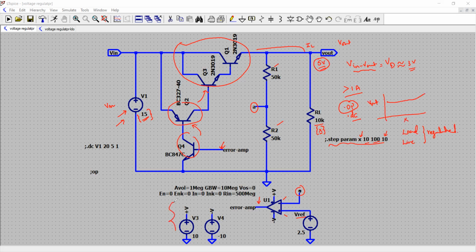We also said that this has a dual power supply that is providing the positive and the negative supply rails to the operational amplifier. And we also covered why we chose these transistors from the manufacturers. We right clicked through the spice library, and we got the specification about IC max and then VCE max of all the transistors. So with that said, now we are going to talk about another circuit, which is a modification of this circuit. So we are talking about LDO.